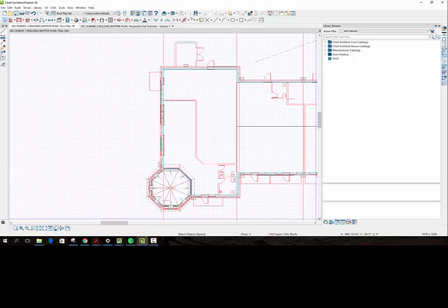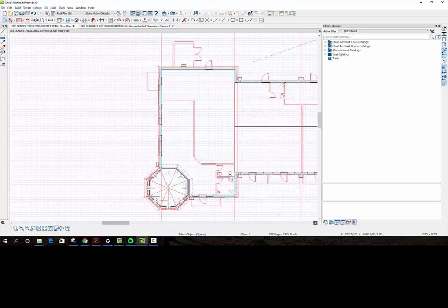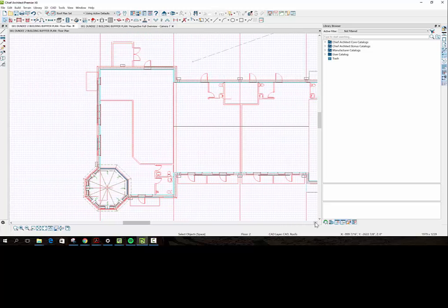A lot of shopping centers, everything goes to the inside. We have roof drains. I really don't want to put anything inside. I don't want to worry about column lines or stuff. So I want the tenants to do whatever they want to do. And it also looks a lot nicer with the scupper box to the outside.